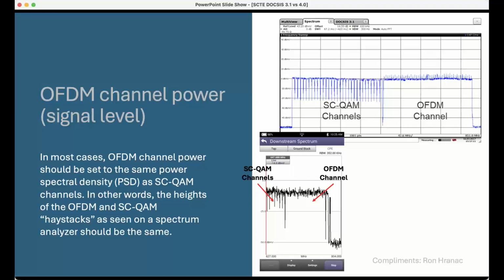It's like having a spectrum analyzer in every subscriber's home. This is one of the best ways to visualize downstream RF spectrum in high resolution. So any issues like standing waves, tilt, suckouts, resonant peaks, and more are going to be visually visible to you when you're doing troubleshooting.